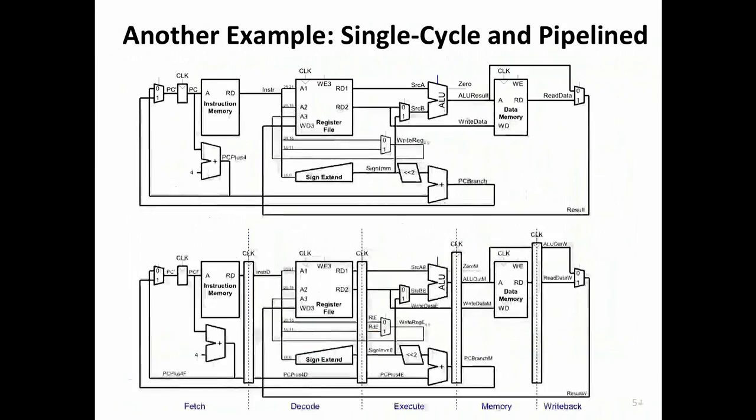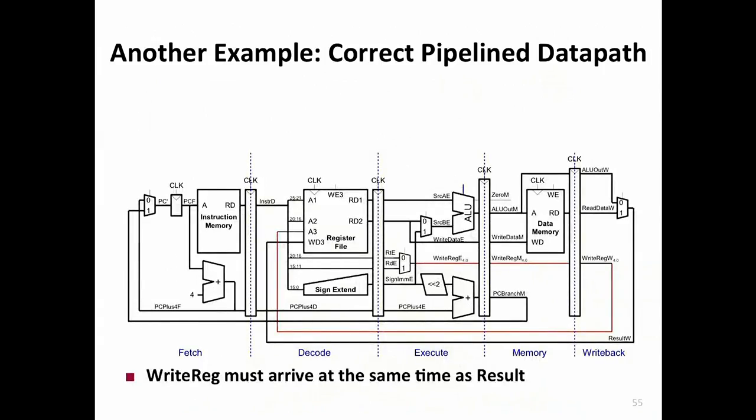Basically, this is a wrong design because it doesn't have that loop back going for taking the write register ID or destination register ID and putting it back over here. It's really coming from here over here. So you need to actually design the data path carefully to make this work. But hopefully that's all not so hard.